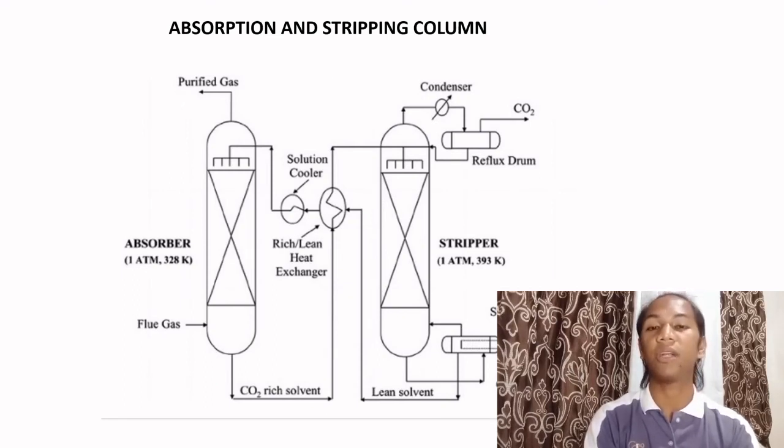In industrial applications, the liquid and vapor streams can have co-current and counter-current flows. Stripping works on the basis of mass transfer. So, above is the example of a combination of absorption and stripper column in some petrochemical plants. The absorber will have the product of rich oil, and that rich oil will serve as the feed of the stripper.